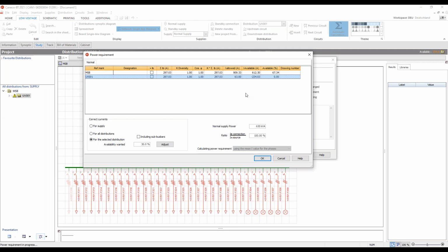So it's a main situation which we have also in the whole project just now, because it's not possible to place a lot of EV chargers in a project which is already finished, where we have just a general power supply and so on. So in that case, we have to check clearly if you are able to place such a quantity of EV chargers in a project, and which cable you have to use, and so on.